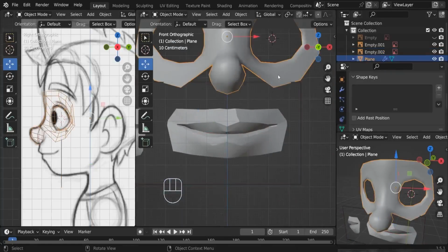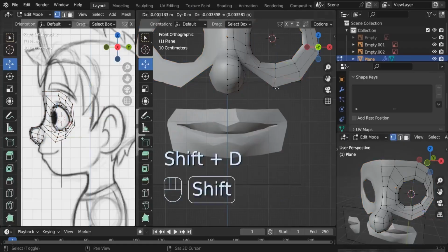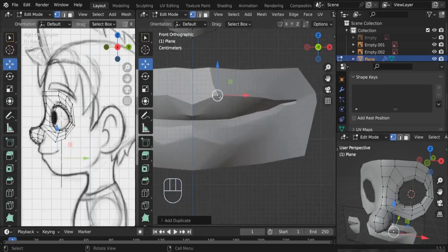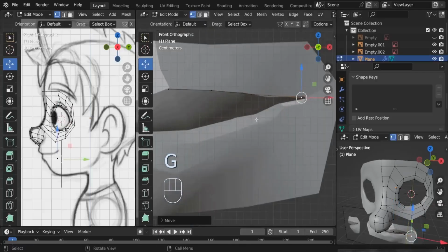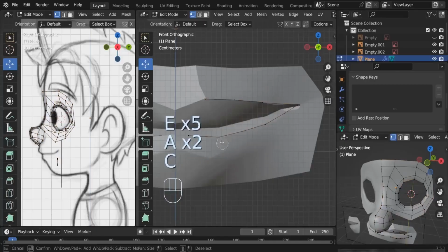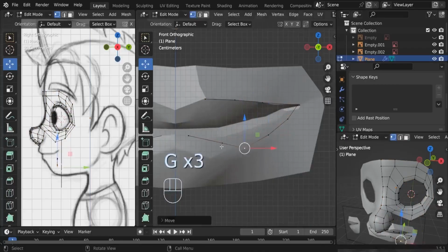So first what I'd like to do is to select our object, Shift D, switch to the edit mode. And I want you to select one single vertex, Shift D, and we can put it, for example, here. All right, so let's go ahead and start extruding. So we can extrude like this, go down to this location. So it's not perfect here, but don't mind that. So we're gonna work on it even better. So extrude down like this, continue that lip. Actually this lip, we should follow it downside. Down here a little bit, something like this.